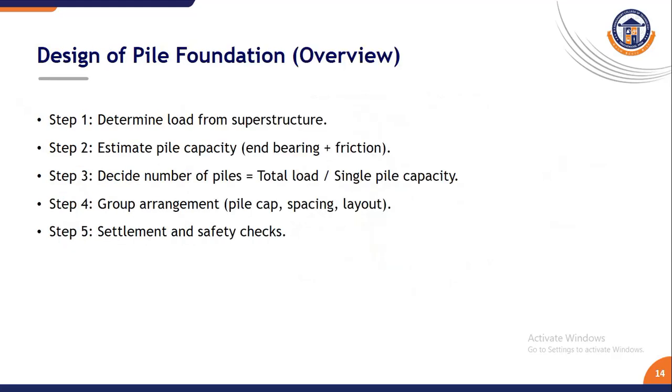Then the design of pile foundation is a process that starts from calculating the total load from the structure, followed by estimating the load carrying capacity of a single pile. The total number of piles is then decided by dividing the total load by the capacity, along with the proper spacing and arrangement under the pile cap. Finally, settlement and safety checks are done to ensure the long term stability of the foundation as the final step. Okay,